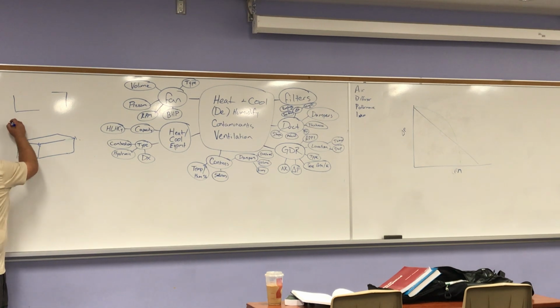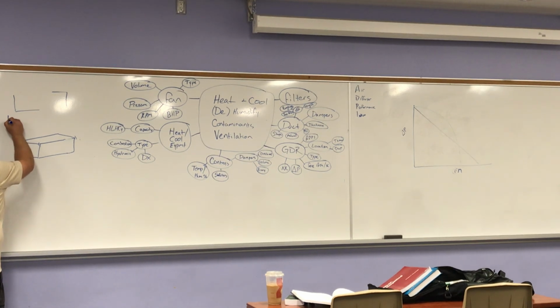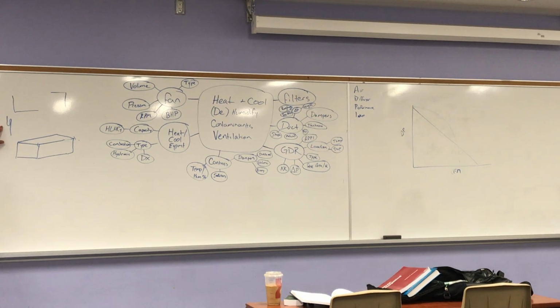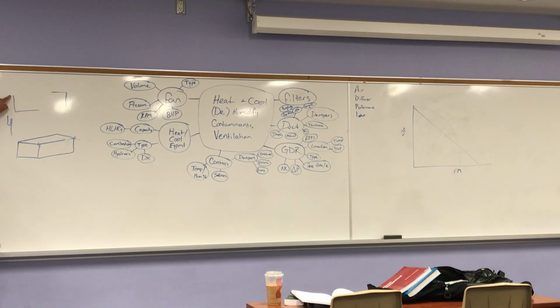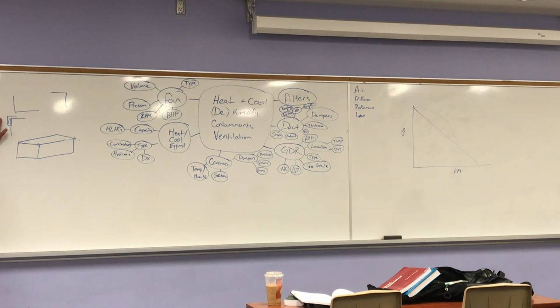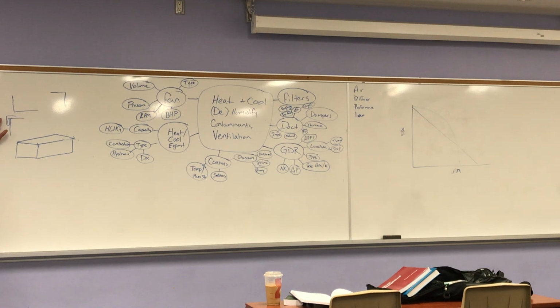And what that looks like is you have a tab that's bent like that. Okay, that's one side of the L up here. And then you have a tab that's bent over like that, and you hammer that over flat, okay? That's fairly tight at low pressures, but at higher pressures it'll start to leak. You need to seal that, okay?